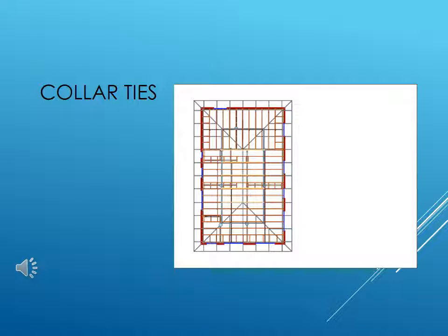And so when you look at a roof side on, and you would have noticed in the assessment quizzes 3A and 3, one of those I asked, what does coupling do, and what are the coupling members? And they are the ceiling joist and the collar ties.